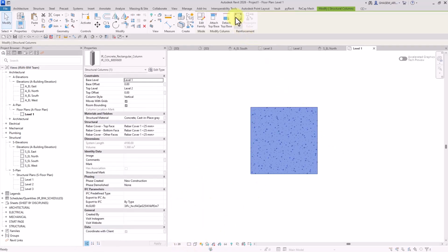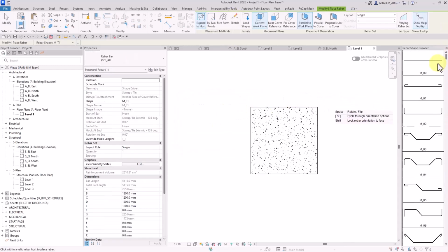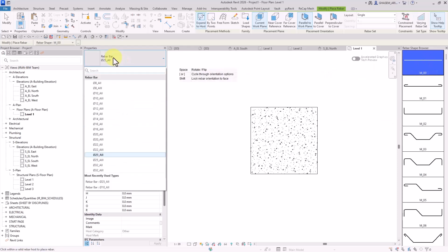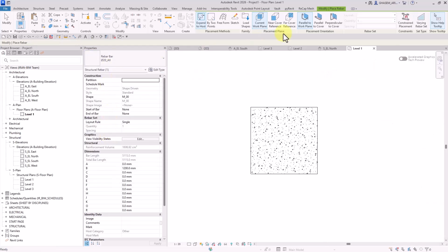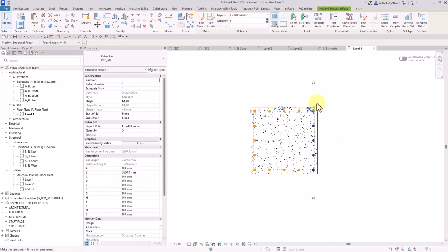Now select, click on rebar, then let's select a linear one and also a type. Then up here by 2 point, perpendicular, and set this on 5 maybe. Now I'm going to select all of these rebars all around our plan. Now I need to deactivate or uncheck all of these checkboxes to prevent any overlaps.